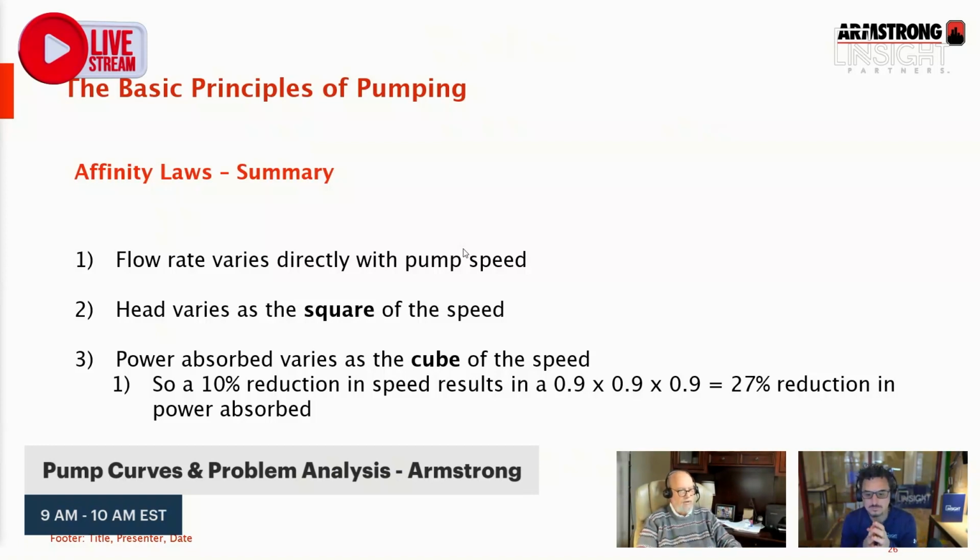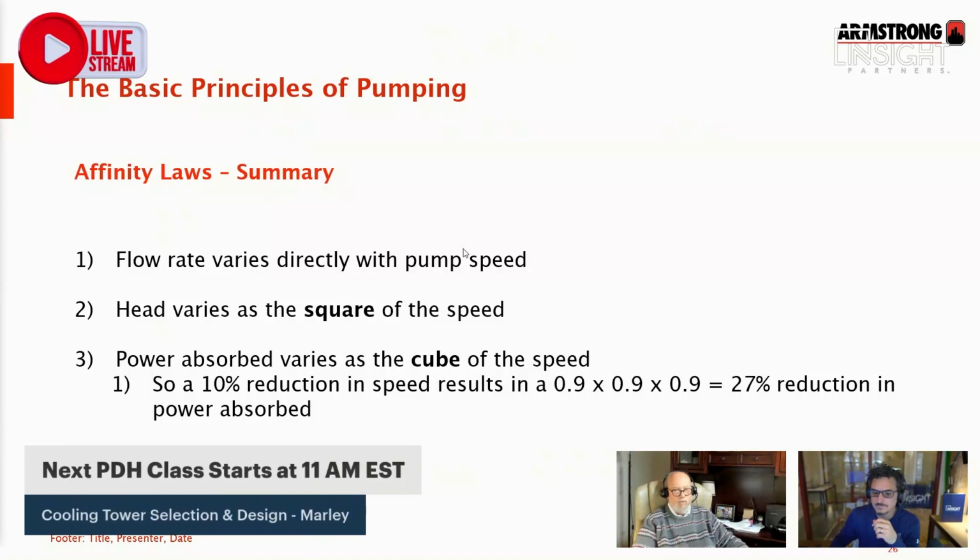That's significant. A little bitty change in speed, big change in power. So start thinking about that. And that's why the energy code says, hey, we want VFDs on pumps. We want variable speed pumping because it makes a huge difference.